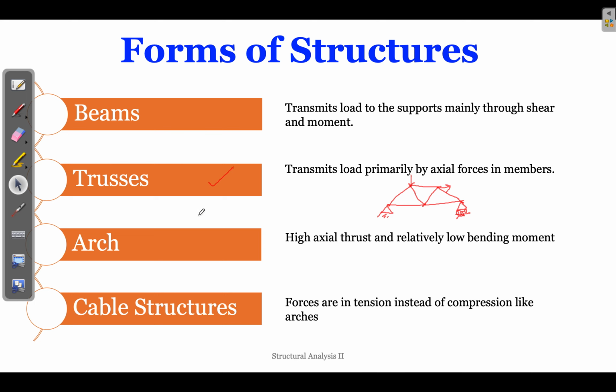And then there are arches. For specific purposes we use arches. It's the shape of the arch, the circular shape of the arch. Whatever load acts on the arches, it actually helps in reducing the bending moment. Because of the arch there is some horizontal thrust acting here, so it does not allow the expansion of the arch, and there is a reduction in the bending moment. So arches are also very useful.